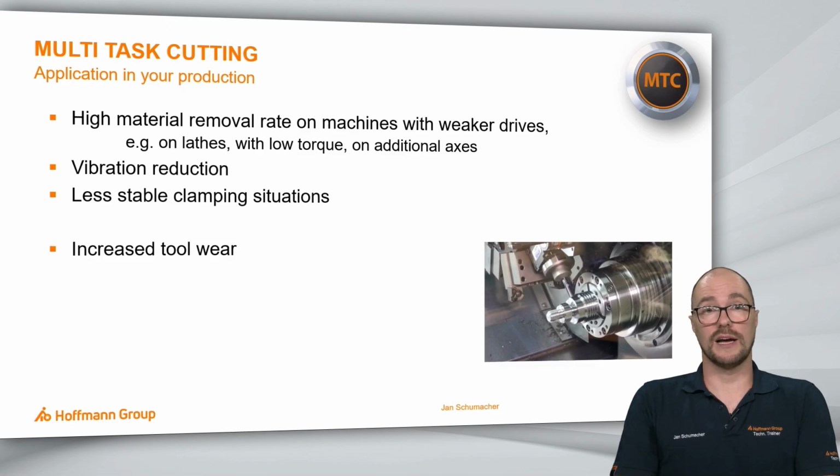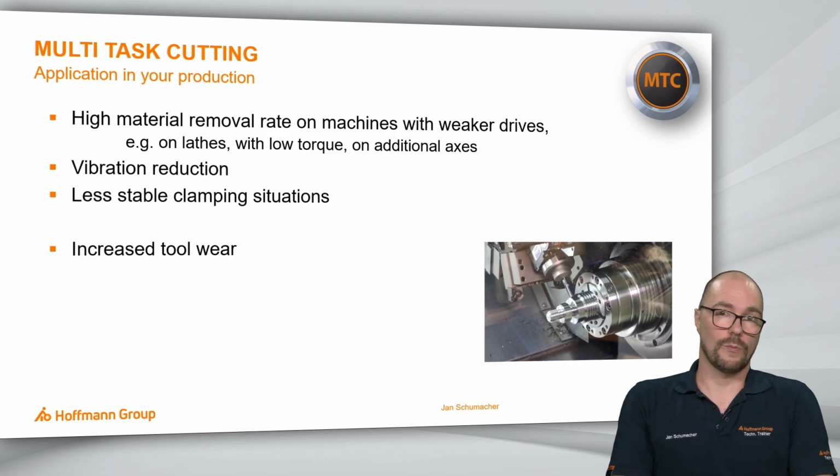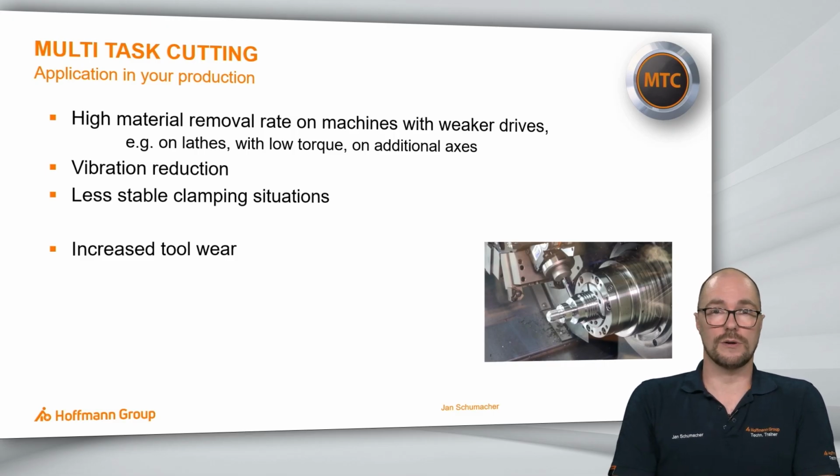As a summary, I'd like to give you the following hints. If you want high material removal on machines with weaker drives or less stable machines, please try one of our MTC cutters. But the downside, of course, is increased tool wear.